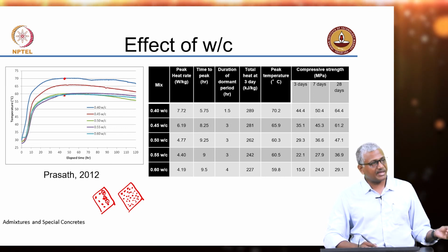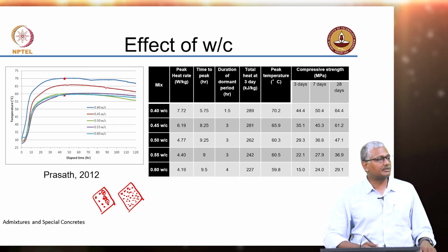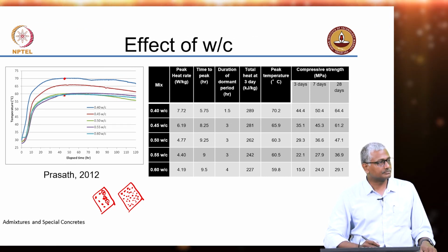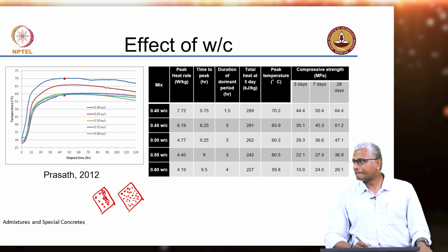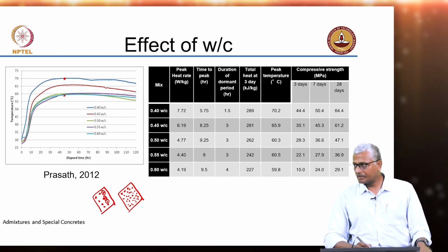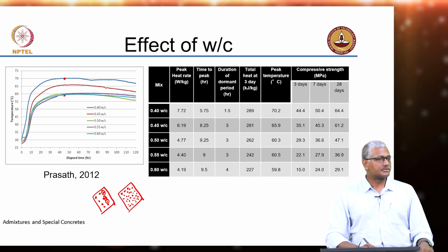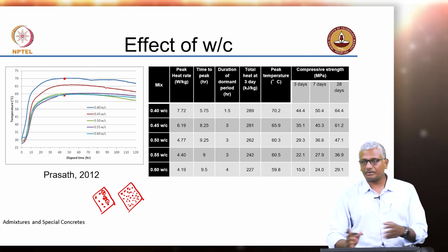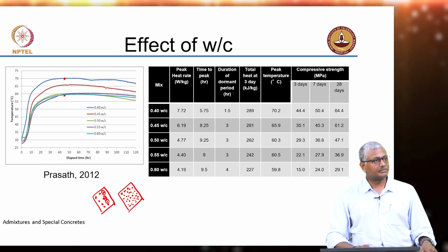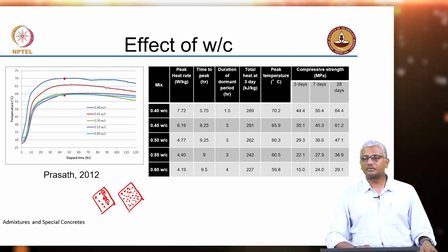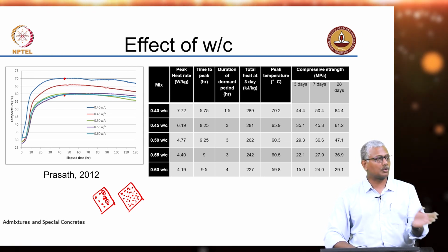which phase, water or cement, has a higher specific heat capacity? What is specific heat capacity? The amount of heat required to raise temperature of a material by 1 degree Celsius. So, does water have a higher capacity or does cement have a higher capacity? If you have to produce hotter concrete, would you heat the cement and aggregate or would you heat the water?